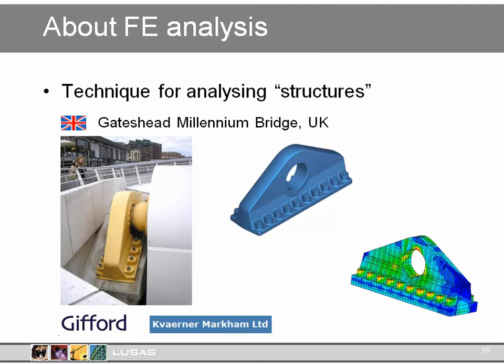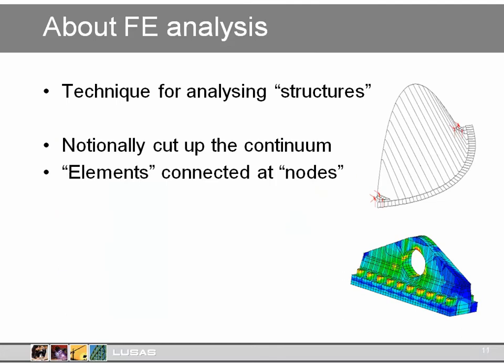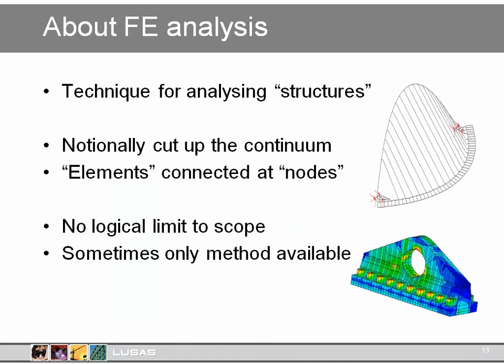And whatever is being analysed, the principle is essentially the same. It is by notionally cutting up the continuum into small elements connected at nodes which can be handled mathematically. The basic principle of subdividing a structure into simple elements can be applied to structures of all forms and complexity. There is no logical limit to the type of structure that can be analysed. Consequently, finite elements provide the most versatile method of analysing structures available at present, and for many structures, the only practical method.